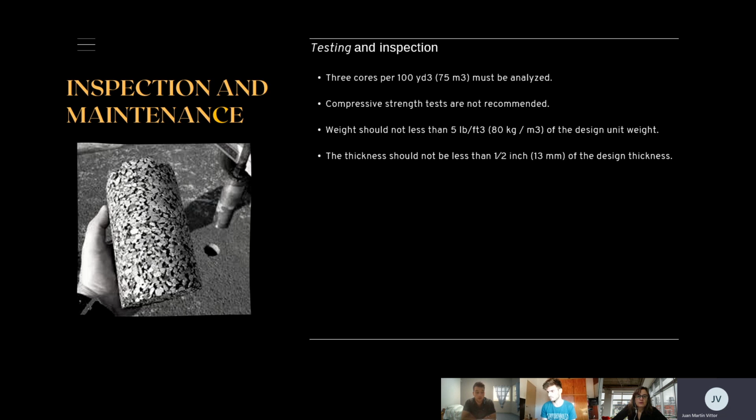In general terms, the permeable concrete doesn't need a lot of maintenance. However, the surface must be kept clean so as not to obstruct the interconnected porous structure, since particles of sand, leaves, and rocks can infiltrate into the voids and impede the free flow of water, reducing the effectiveness of this material.